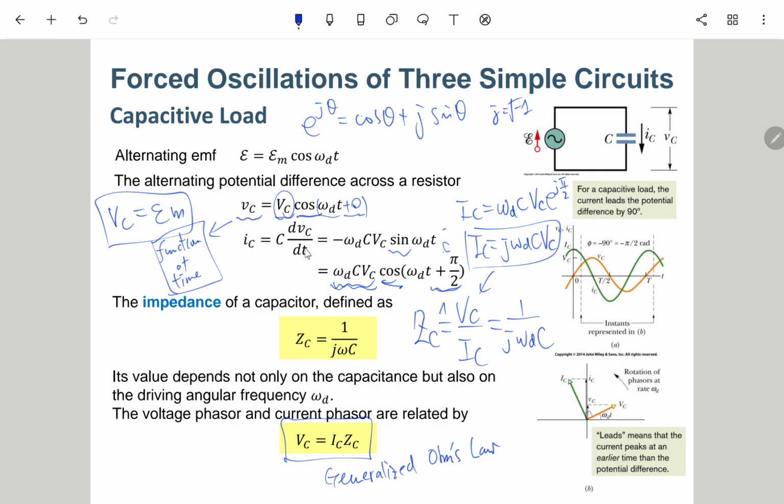Here we try to introduce the complex number. Playing with the complex number is at least easier than solving the ODE. So the idea of phasor is like this. We try to create something called phasor, so that we just do the computation with complex numbers rather than taking derivatives of a function of time, or solving a constant coefficient ODE.